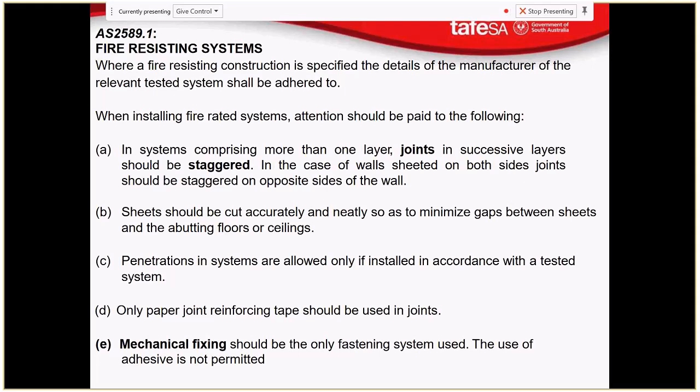Can anybody think of why that would be? Why would we get much better acoustic performance with staggered studs or double leaf walling? You've got a break. Yeah, exactly. Not continuous. Yeah, exactly. We don't have any continuous connection from one surface to the other surface, because sound transmission happens in several ways.